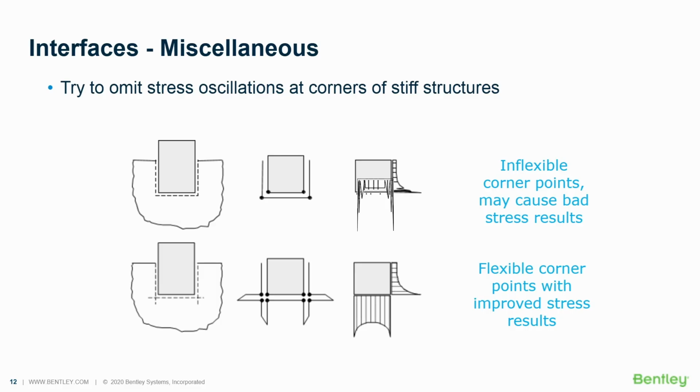You understand that this will generate for those pairs of nodes an incompatible mode of deformation, okay? And usually during the calculation, this will result in bad, shaky, I should say, stress results, which are moreover inaccurate and can possibly provide artificial additional bearing capacity eventually.